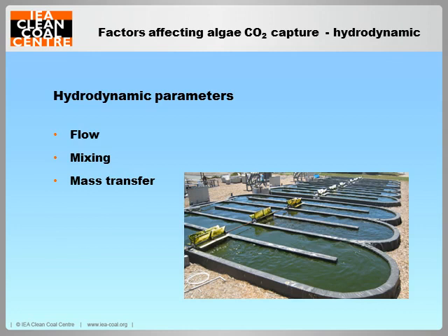Appropriate turbulent flow and mixing are necessary to homogenize the cells' light, heat, nutrients, and metabolite distribution, to enhance mass transfer and to prevent microalgae aggregation and sedimentation. Mixing also takes advantage of flashing light effect, which increases algae growth. Excessive turbulent flow and mixing may damage the microalgal cells, besides requiring a large energy input.